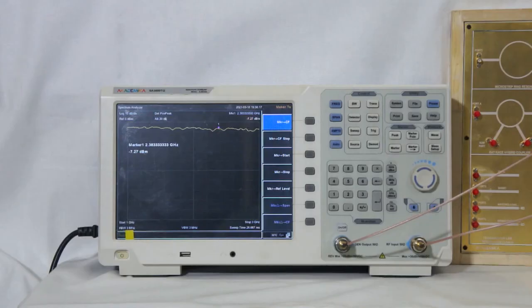The displayed plot on the spectrum analyzer shows the insertion loss, that is S31, or power division for the signal measured at port 3 and RF input at port 1. Displayed plot shows the insertion loss S31 is around minus 5.4 dB at 1.4 GHz, which includes a minus 1.2 dB loss of the RF cables. This means 3.2 dB power is transmitted at port 3, which verifies the design specification.